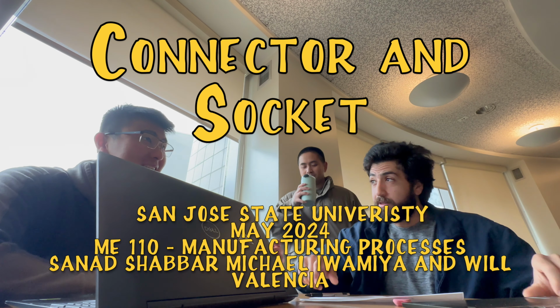For our tolerancing scenario, we analyze this connector and socket that is used for a USB-C adapter. Connector and socket geometry typically include a male and female part, with the male part designed to fit into the female part. The size tolerances will define the allowable limit in the size of the connector pins and the socket holes. Positional tolerances will also be applied to the location of the pins and holes to ensure they align correctly.